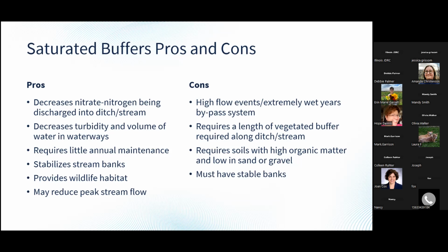And then also it requires that length of a vegetated buffer area along that ditch or stream. So like I mentioned, you either have to have one of those buffers available or be able to put one in. And it requires soils with a high organic matter and low in sand or gravel, and there must be stable banks as well.